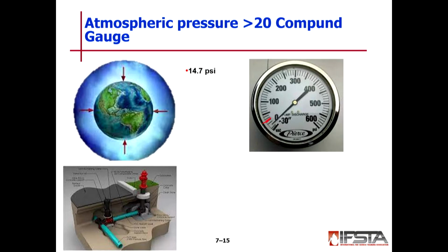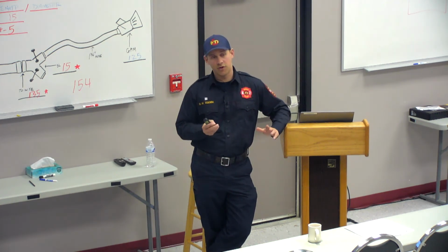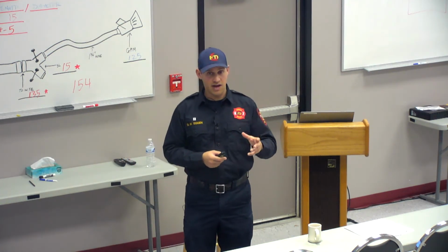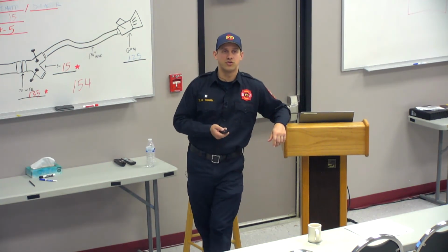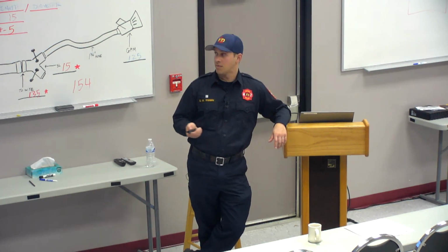pushing on us. Theory is, and Mr. Goodman can probably correct me because he's a plumber. He knows a lot about this stuff. When you have water moving through those pipes or even static in that pipe, they have an amount of pressure built up. It's like a static pressure, right? And that pressure is always pushing out on the walls of those pipes, those hydrants, or 5-inch or hand lines. That's why they get hard. When those numbers start to drop below 20, that is showing you the amount of pressure left in those lines all the way back to the water mains and feeders.